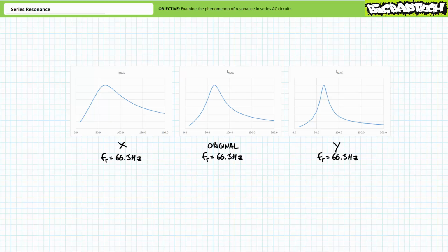The generally accepted standard for gauging selectivity of a circuit is the range of frequencies inside of which the circuit experiences half power or greater. For this reason, the left and right boundary frequencies of this region are often known as the lower and upper half power frequencies, F1 and F2. They are also known as the cutoff frequencies, the band frequencies, or corner frequencies, depending on which industry jargon you're employing. Operating the circuit at any frequency inside this band would experience half power or greater. Operating the circuit at any frequency outside this band experiences half power or less.